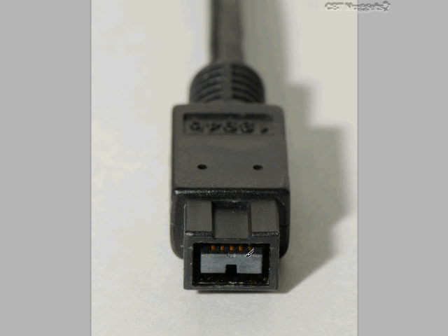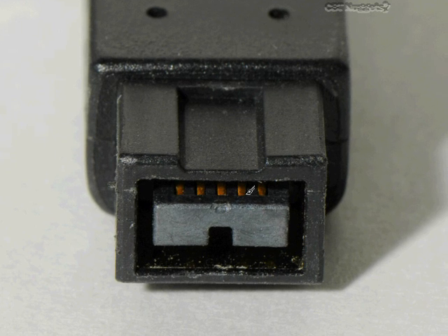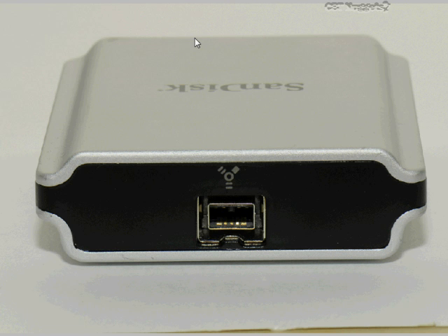Now, also by way of example, this is a photograph that I took of my actual 1394B cable that I'm using to connect to a device right now. You can see a little bit more clearly here the 5 pins there. And we also see this notching right here, this keying up here at the top. This would be identified as a bilingual cable because, indeed, the other end of this cable is a 1394A connector that plugs into the back of my computer. And then this is what it's actually plugged into right now. This is a SanDisk card reader for compact flash. By the way, there's the symbol for FireWire, just so you can easily identify that.